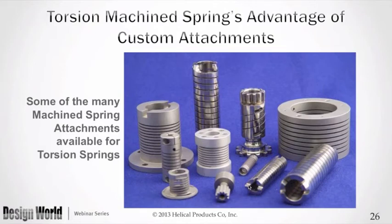But we can also put slots in these things, and there are ones with slots. That one with slots is interesting. You might want to take a note of it. That's made out of 38644 beta C, and because beta C is a special alloy that has a body-centered cubic structure, it doesn't creep under load, and that spring sits at about 85%, maybe even 90% of yield for years before it gets used. So that's kind of an interesting machine spring.